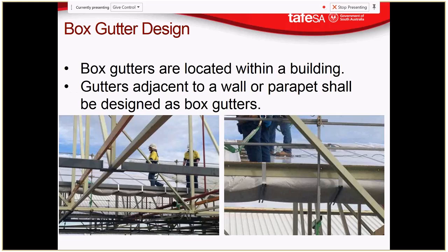Question: who should design the box gutter? Is it our responsibility or duty? Yes, it really should be the designer's responsibility because it impacts so much. When you're designing the building, if you're designing in a box gutter, you want to know whether that box gutter can fit. You don't want to go and tell somebody else, can you design this box gutter for me, and they design one and it doesn't fit within what you're designing. Because it impacts so much on your work, it's much better if you can do that box gutter design yourself. And as I'll show you later on, it has been made really simple with online calculators for designing box gutters.